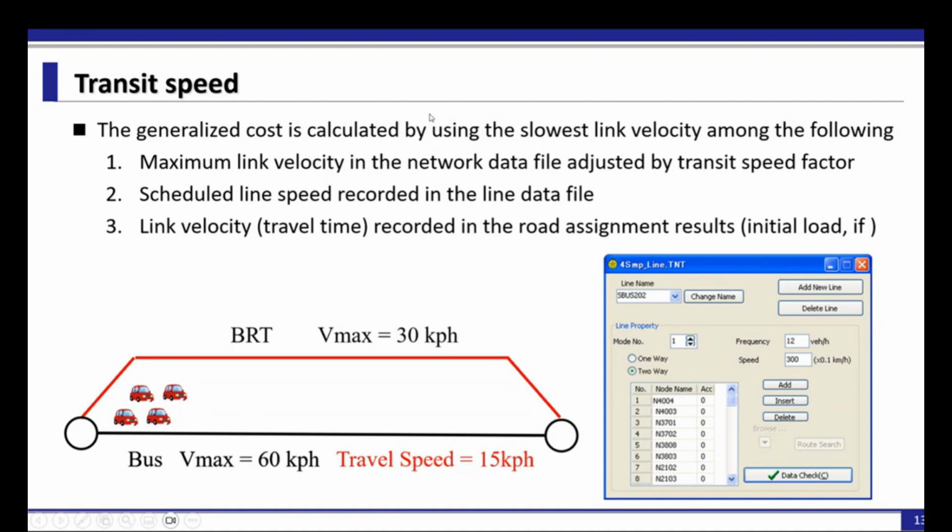If you would like to reflect the actual conditions specific to the road traffic among the cities, it is recommended to develop the initial road traffic OD tables. However, if you want to skip that kind of estimation method, you can just specify that in the congested sections the travel speed should be slower, by typing 15 kilometers per hour as the travel speed for the sections.